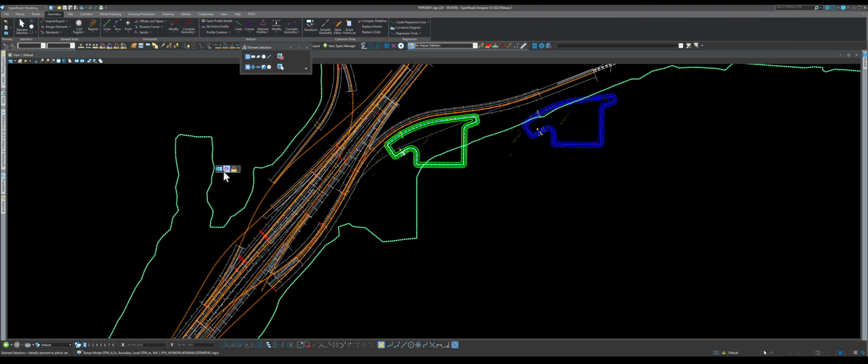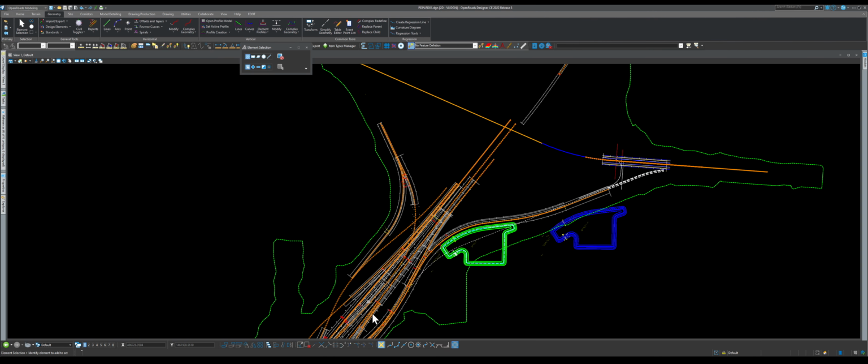But right now I don't want to do it this way. I'm going to show you another way in case y'all don't know about it. Go here to the geometry, just draw a line, any line, and then go to the vertical section here and do profile by constant elevation. Click on it, and then type whatever elevation you want here. 2, 3, whatever, 25, it doesn't matter.